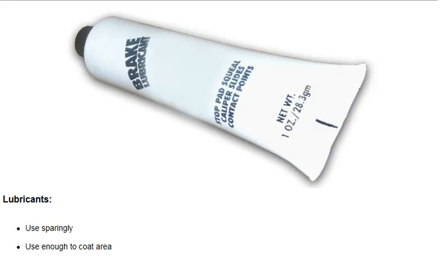When applying brake lubricants, be careful about the amount of lubricant used. It should be used sparingly, but enough should be used to coat the area on which it is being applied.